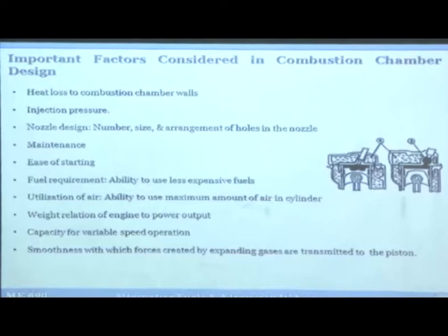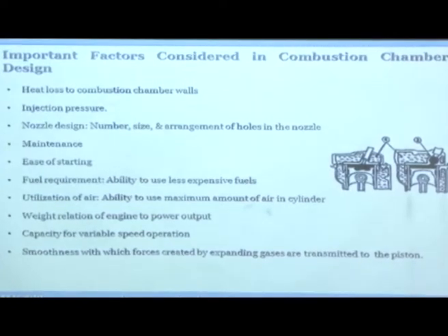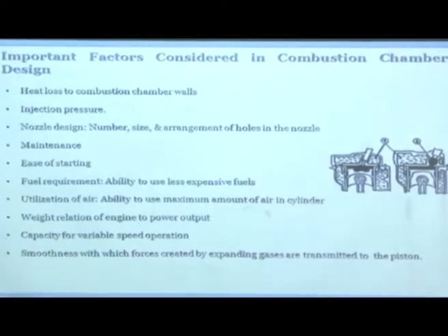Then there are some applications where you don't want very expensive fuels, you really want very cheap fuels. For example, marine, I gave you an example of marine engines where it is required that you use very cheap fuels. So the ability to use less expensive fuels is also dependent on your combustion chamber design. Then utilization of the air. Basically you would like to utilize the maximum amount of air possible in the combustion chamber. Then the weight relation of the engine to the power output is also affected by the combustion chamber design.